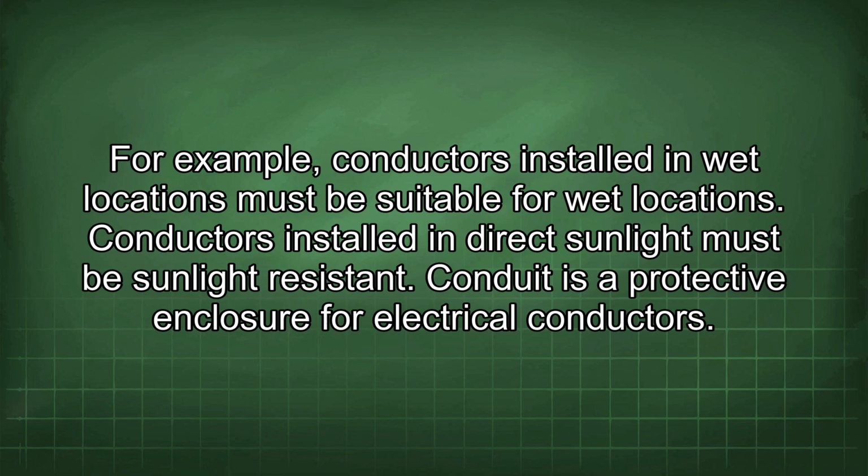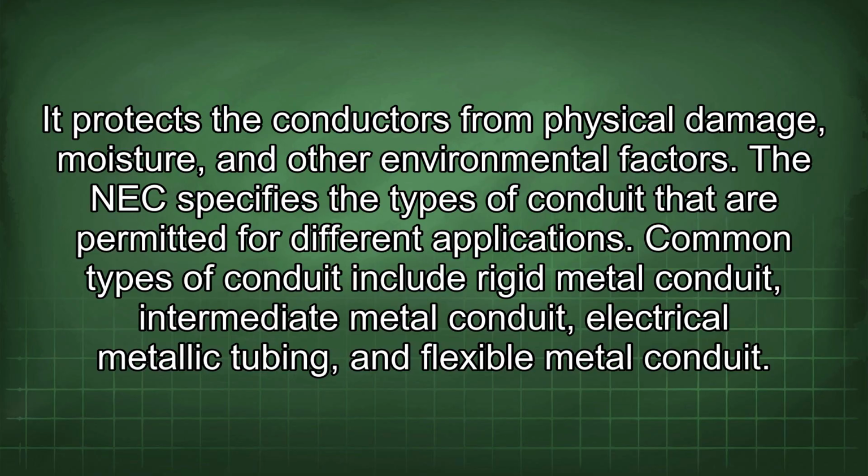Conduit is a protective enclosure for electrical conductors. It protects the conductors from physical damage, moisture, and other environmental factors. The NEC specifies the types of conduit that are permitted for different applications. Common types of conduit include rigid metal conduit, intermediate metal conduit, electrical metallic tubing, and flexible metal conduit.